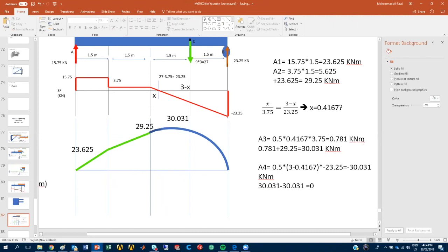So again, thank you to Thais and Matthew. And that's what I was meaning. So thanks. Yeah. So now it's corrected, looks better. And that's one of the things, guys, you always need to remember in your test. When it's a triangular load or UDL, on the bending moment diagram it should always be a curve, parabolic. Otherwise, you may lose marks like I'm doing now for myself, because of many things going around. So that's how you do it. In your test, I don't expect you to have a proper parabola, but as soon as you show it a bit curvy, that will be more than acceptable.